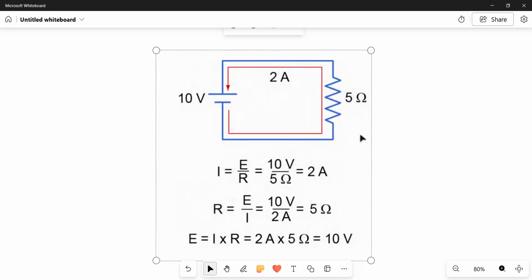So I said, man, but even so, and the electrician in the class here should tell you, if there was a ground wire attached to the point that they were using, that should have taken the current to the ground. Am I right? Yes, sir. And guess what I found out? They did not have a ground wire in their entire house.